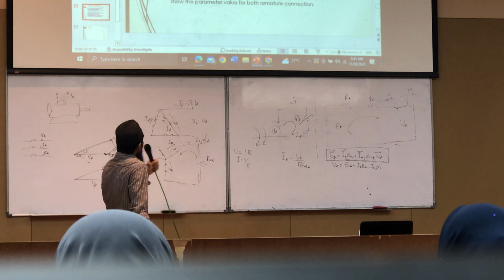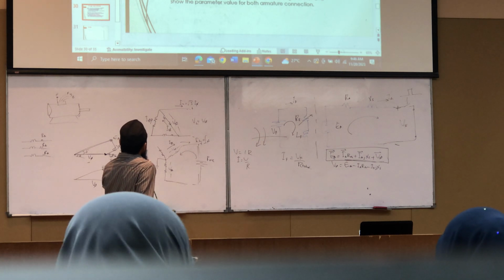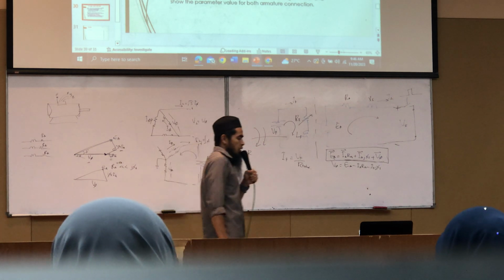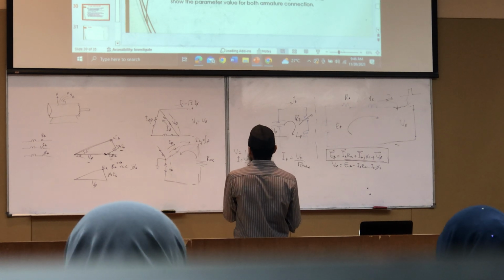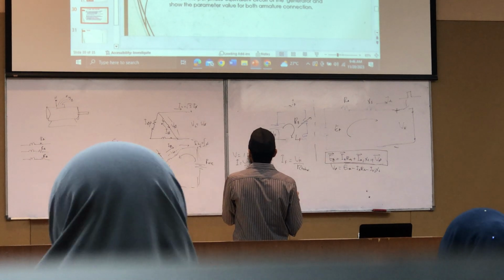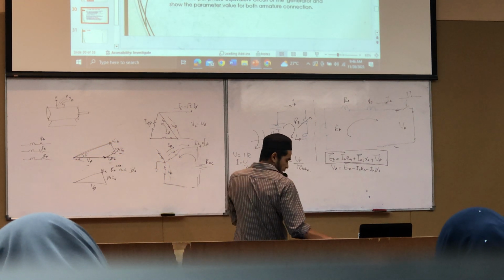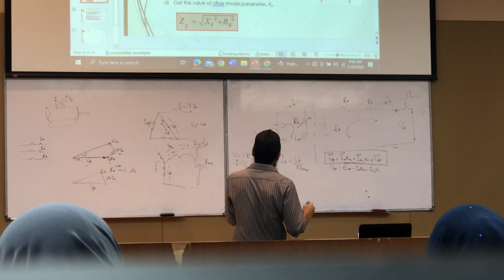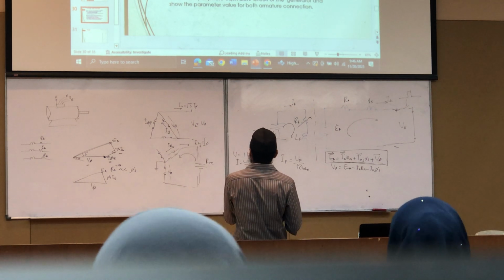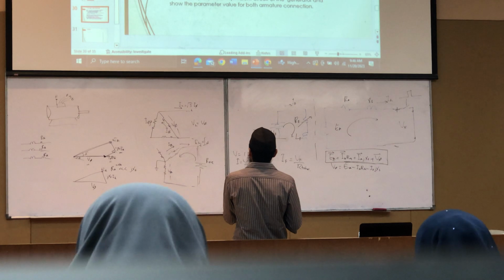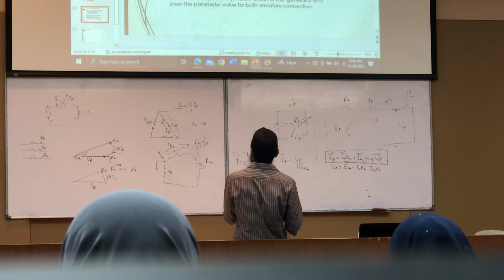Okay, we have a few minutes. We try to take a look at this exercise. We have a scenario with a 200 kVA, 480 volt, 50 Hz synchronous generator with a rated field current of 5 ampere. The rated field current, this one we have tested, we consider as 5 ampere as our result. Then we measured V terminal open circuit to be 540 volt.